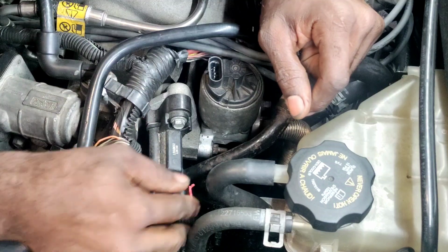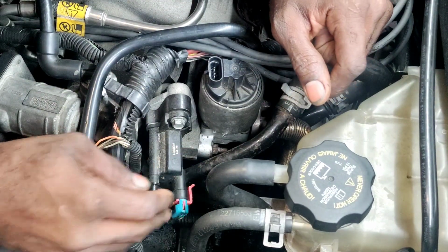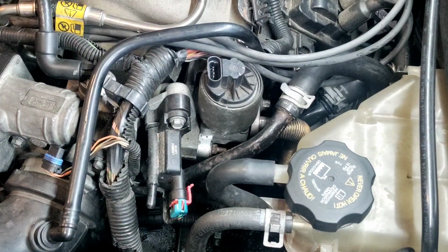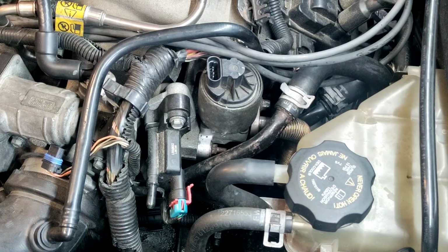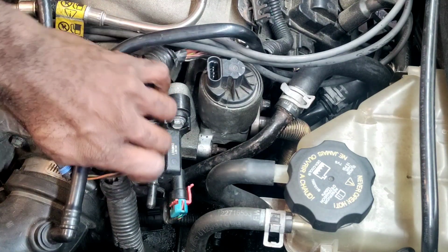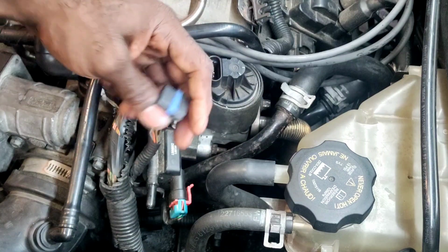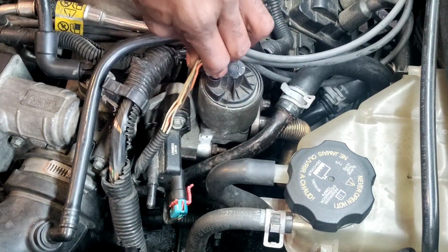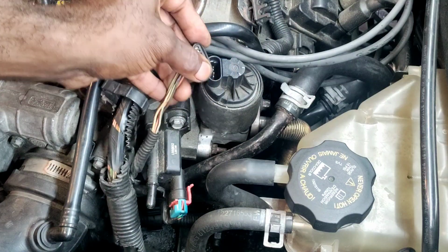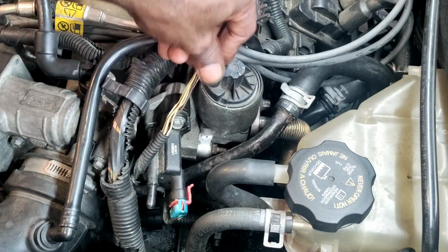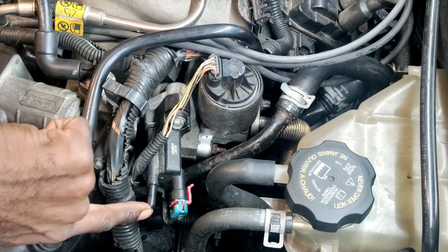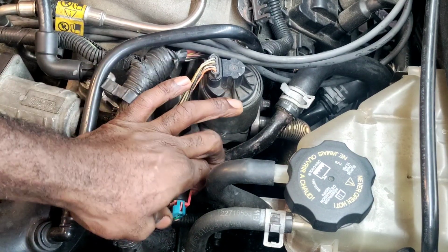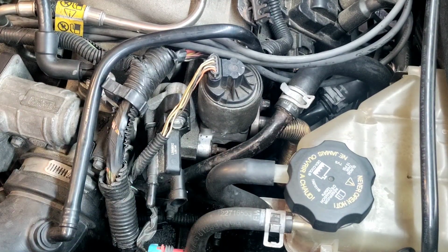Usually these leak, so it might be worth just trying to put a hose in there and blow through it and see what happens. I could just start it up and see if it has air going through here, which I'll go ahead and do right now, and that'll answer my question, because if it does have air, then this should be closed. Let me just disconnect it. We already got a code for it.